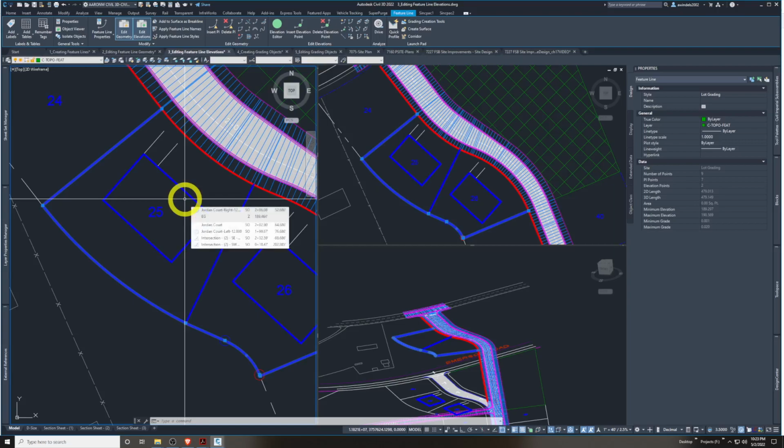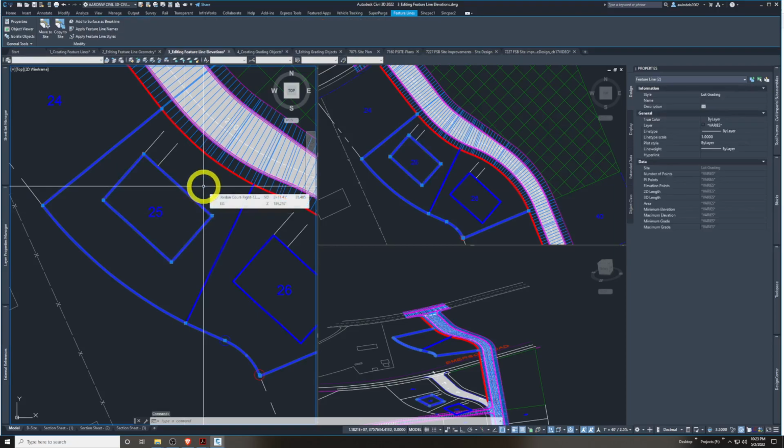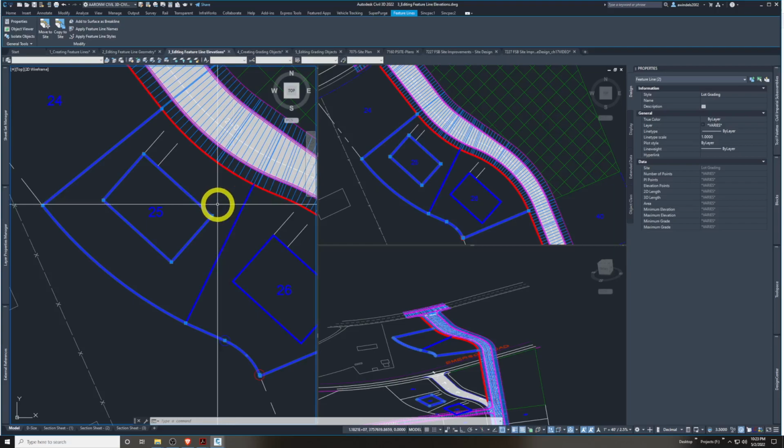And one of the key things of a building pad is setting a really good elevation of maybe where the foundation starts to be built on, or later if you add from the ground up, that would correspond to a finished floor elevation. So setting some of the critical building pad elevations is one of the huge, bigger things that dictate grading design for things like land development here.